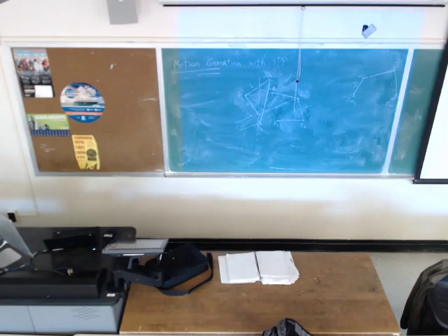The intersection is going to give me O2. Repeat the steps for O4, but this time I'm going to use B1, B2, B3. And as I said, we can draw the line between B1 and B3 and draw the perpendicular bisector. It's going to pass through O4. So this is how you can find O2 and O4.